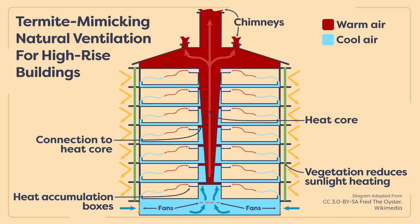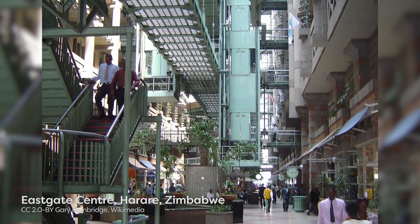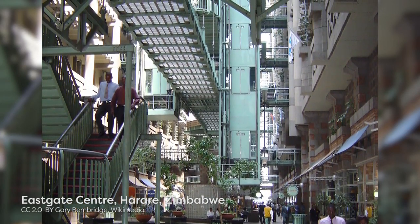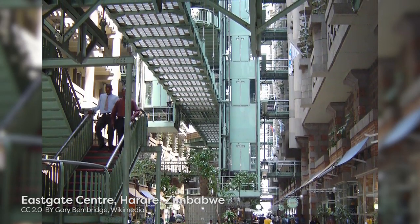Air is drawn in by fans on the first floor and either warmed or cooled by the mass of the building. The air is then directed into the floors and offices before it eventually exits the top of the building via chimneys. This design saves on air conditioning and heating costs, which translates into a 20% lower rate than market averages for tenants in the building. The Eastgate Center is a symbol of the possibilities of biomimicry.